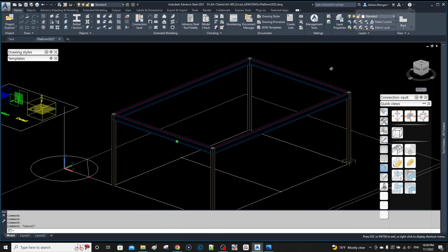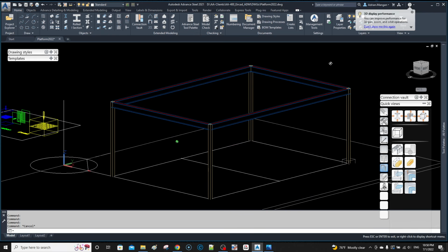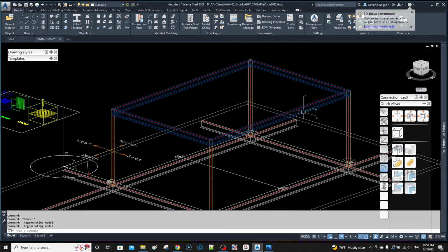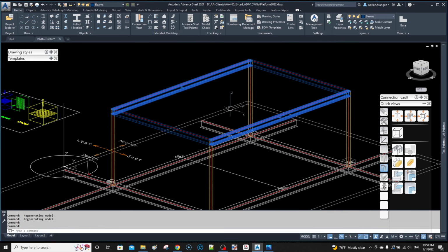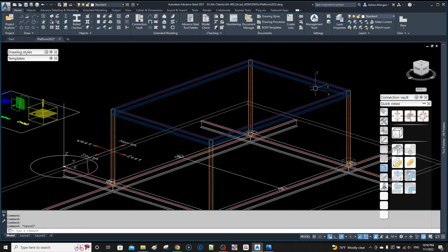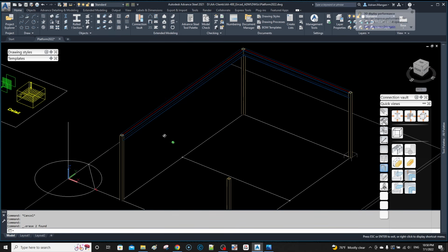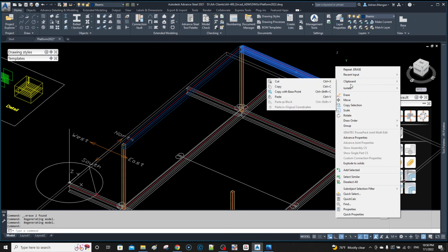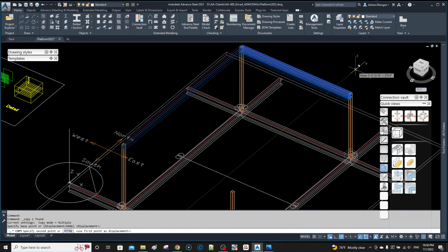So I've put in those beams now, but I am not happy with those beams because this one is modeled in the opposite direction of that one, and same here and here. So what I can do is I'm going to delete these two. Generally, good practice is to model all your beams, your columns from down to up, and your beams south to north and west to east. So I can copy these if you want, because these were already created correctly.